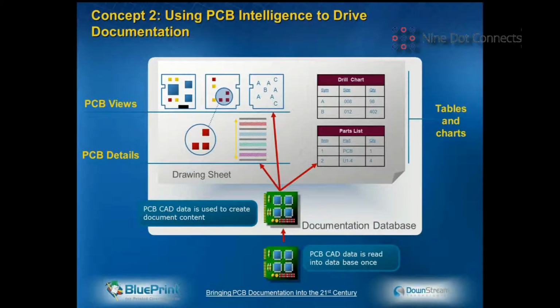We wanted to use the PCB intelligence to drive the documentation. Everything from a parts list, a drill chart, to a layer stack up, to top and bottom side views, we can extract all that information from the PCB design. It's just different views of the PCB.